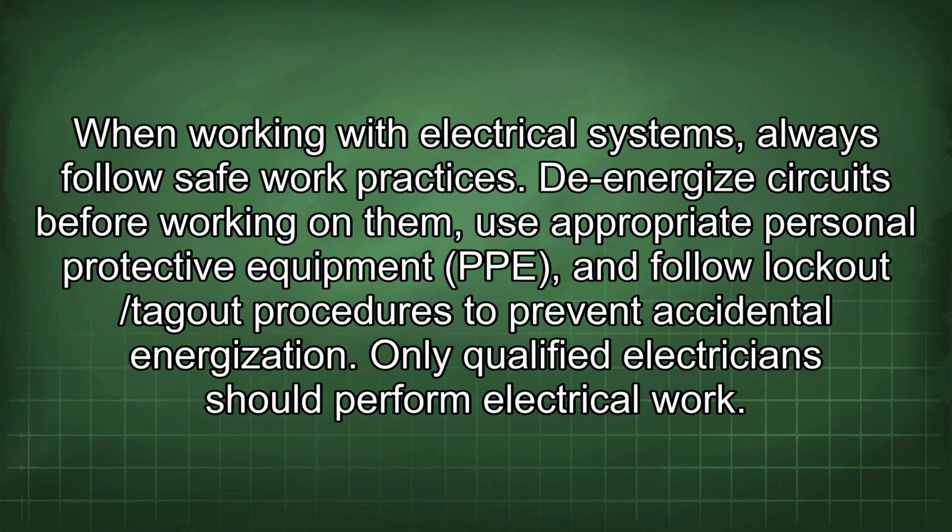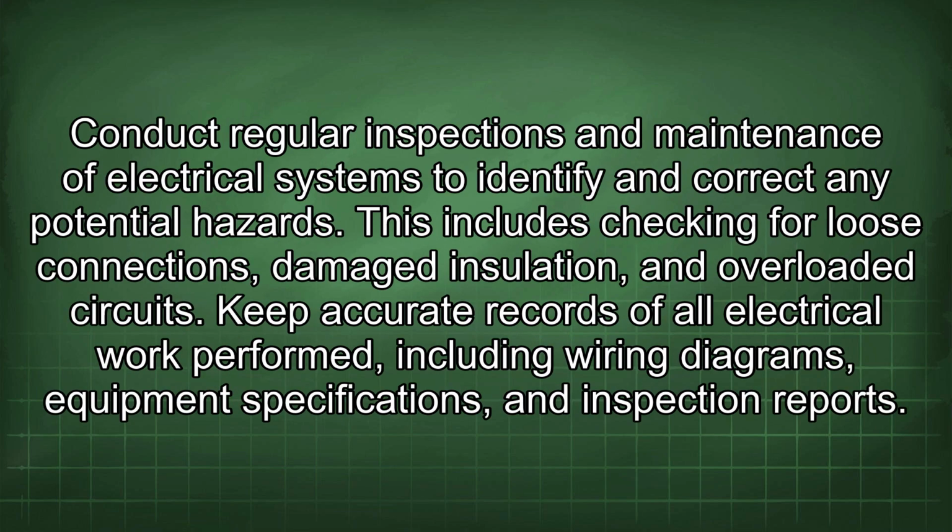When working with electrical systems, always follow safe work practices. De-energize circuits before working on them, use appropriate personal protective equipment (PPE), and follow lockout/tagout procedures to prevent accidental energization. Only qualified electricians should perform electrical work. Conduct regular inspections and maintenance of electrical systems to identify and correct any potential hazards.